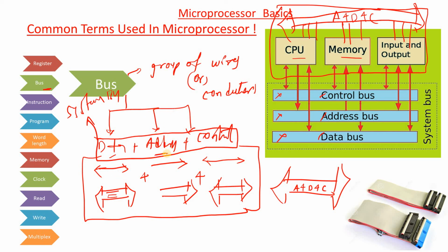The address bus is always unidirectional and it is used to access one location in the memory. For example, if it is a memory, a number of locations are there, and every location has a unique address. With the help of these addresses, we first highlight the location. Only after pointing or selecting can we perform either a read or a write on this location. That means the address needs to be accessed initially, with the help of the address bus only. So the address bus is unidirectional: we point to one location in the memory, or we select one IO device in the external world.